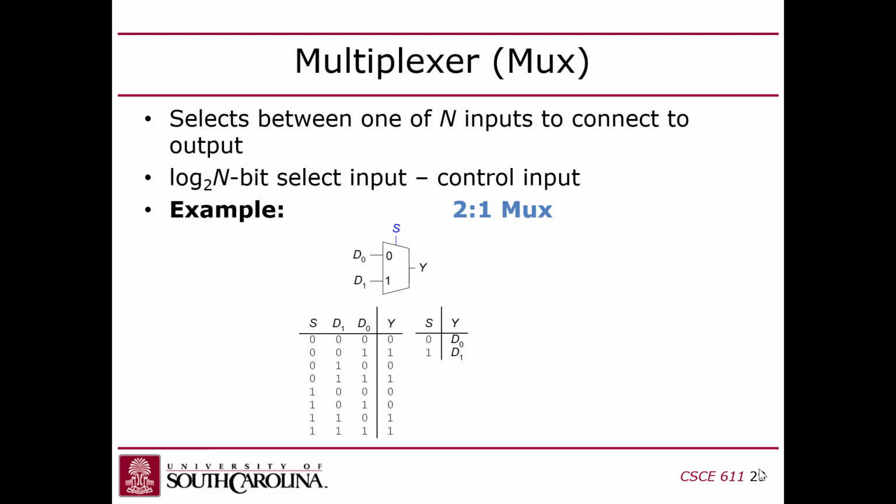The ALU, for instance, allows me to add the contents of 2 registers, or I can add the contents of 1 register with an immediate value, right? So that would be another mux I drop in there to select between whether I want to add 2 registers or 1 register and the immediate, right? There are options.